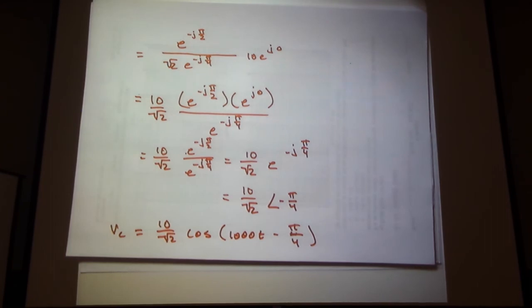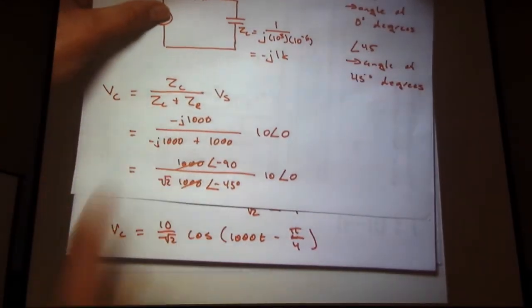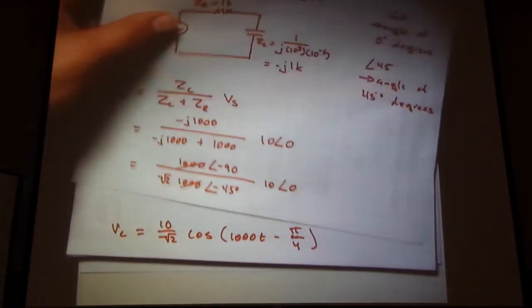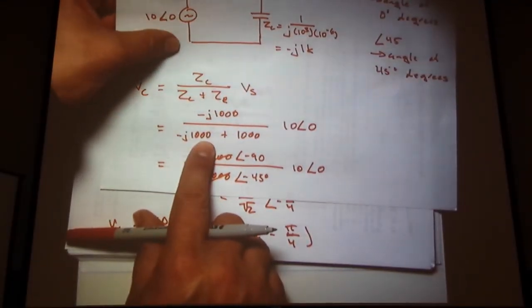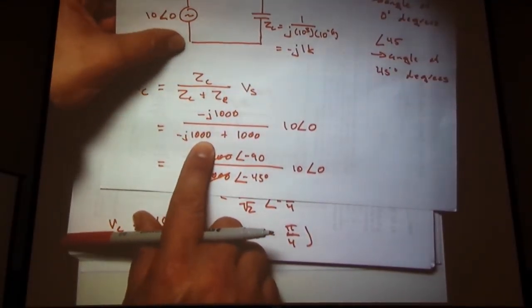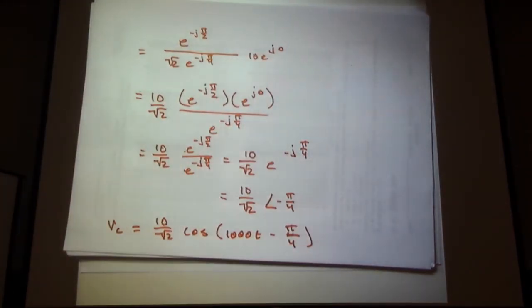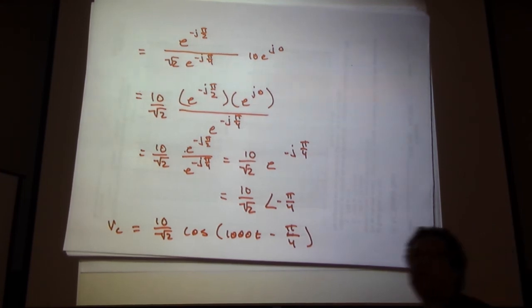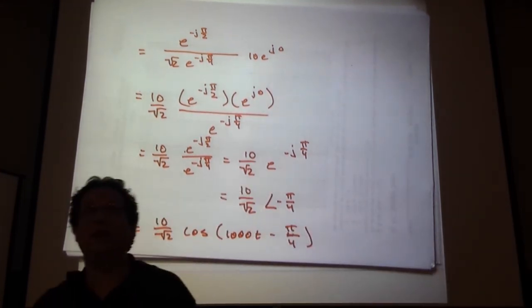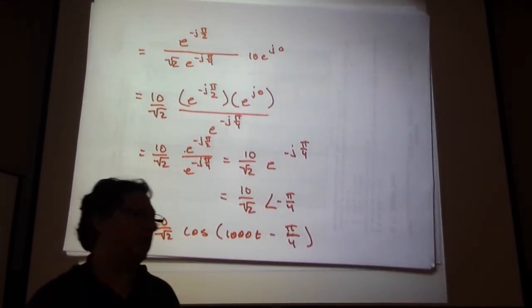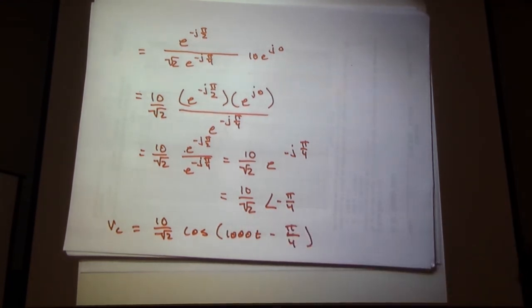We build the circuit the same way: ZR, ZC, ZL, if we have ZL. We convert that now to a complex or imaginary term, as the case may be. Convert everything to a phasor expression, and we'll use those tools to find amplitudes and phases, to find our response. All right, so there's our introduction to phasor analysis.